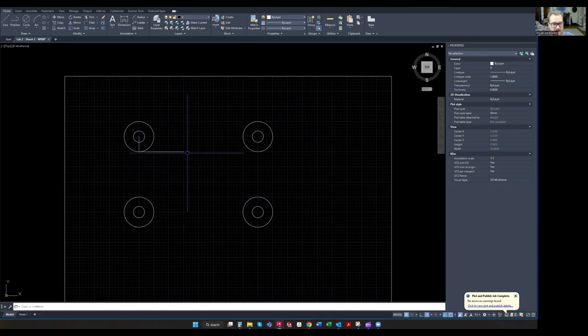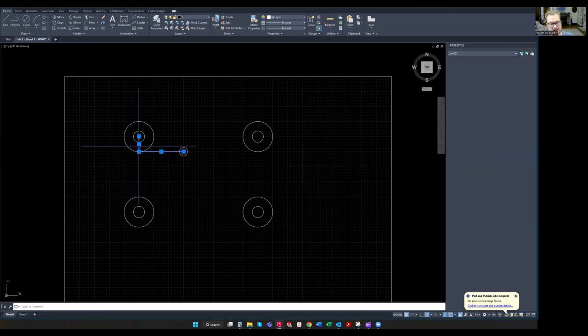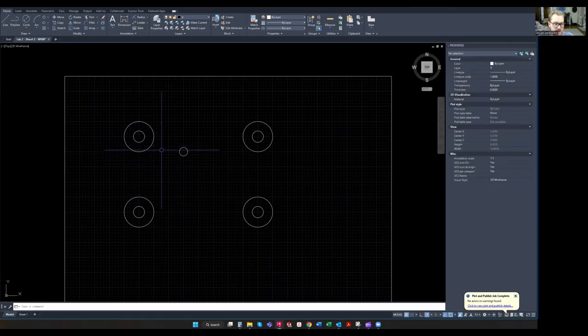So now we have two lines 90 degrees perpendicular to each other, 1/2 inch down, 1.5 inches over. And this is the point for our next circle. So we're going to grab our circle diameter tool, starting at this point that we've just created, make that a 0.281 inch diameter circle, enter. Now, before we do anything else, let's go ahead and delete these two lines. So just click on both of them and click delete on your keyboard.